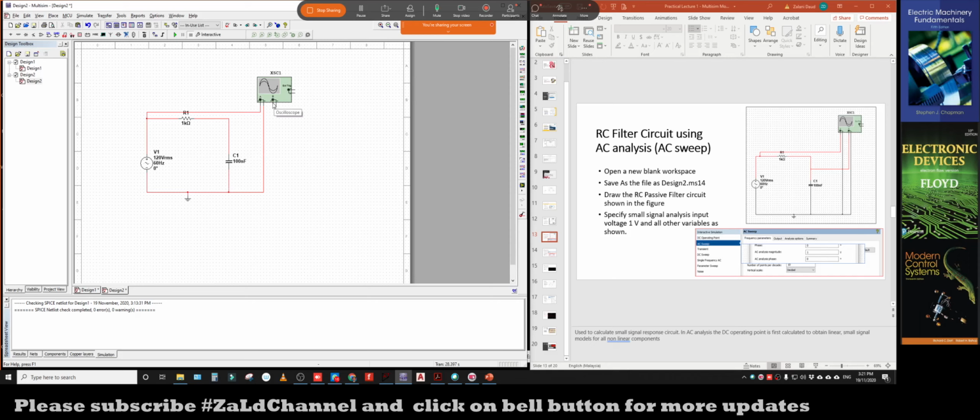Similarly, for B, now I'm going to measure the output across the capacitor, the output signal. So I will connect one terminal of the capacitor, and the other one, as usual, I will connect to the ground. Make sure that the negative terminal is always connected to the ground. For signal B, we want to measure the output signal across the capacitor. For signal A, we want to measure the input signal, which is from the source. All right, so that's all of the connection.